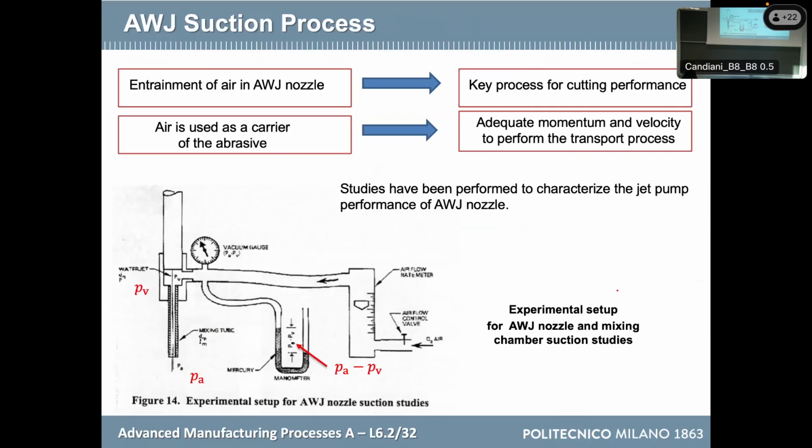There is something misleading. I would say that PV is a result. PV is not doing anything here. It is not used for anything for now, because I have clogged. So no need of attracting air. There is no air. There is no possibility for the air to enter. And so the vacuum is still there, but is it higher or lower than before? Lower pressure, yes. More vacuum, lower pressure.